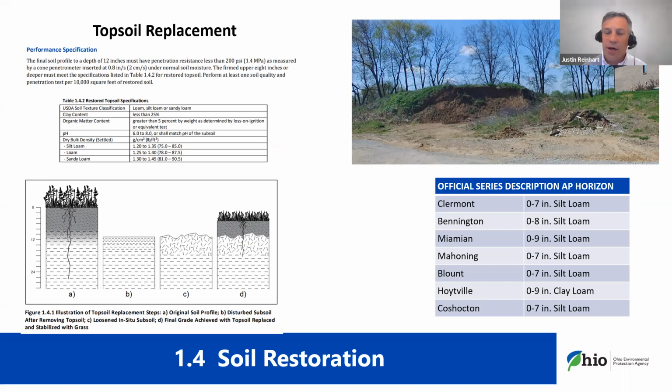the first of which is topsoil replacement, which is essentially stripping that upper layer of high quality, loamy, organic topsoil and spreading it back on the area after construction is complete, which involves an intermediate process of some mixing that needs to occur to alleviate that light compaction and sealing, so you don't have a stratified soil. You can see the step-by-step process in the rainwater land development graphic from A, B, C, and D, where topsoil is existing, it's removed for our grading work, then we have that area broken up and the topsoil replaced to a level that can support healthy vegetation.